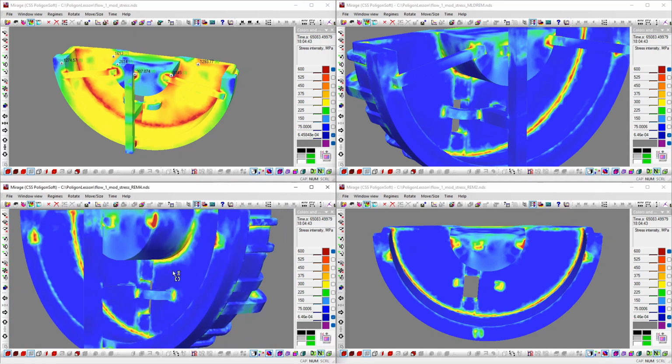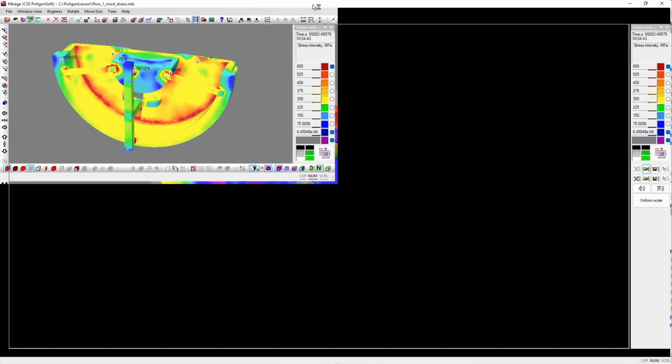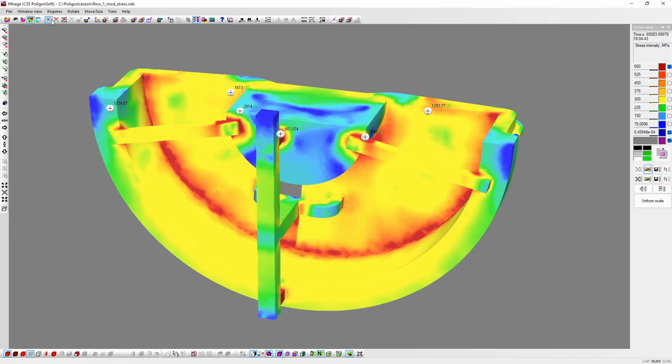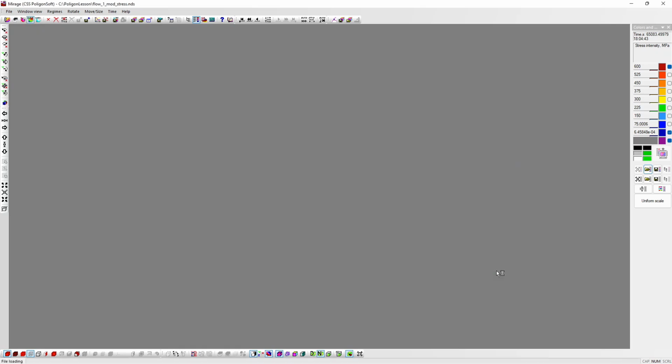As for possible fractures, let's look at the additional field that we have recorded. The intensity of plastic strains. That is, only plastic strains, without the elastic component. We load additional data through the Open Universal File button. And here it is. We have 4 files with plastic strains. Since plastic strains accumulate, unlike the elastic component, we can directly see the level of plastic strain at the time of the last operation. I open the file for plastic strains after the removal of all elements.